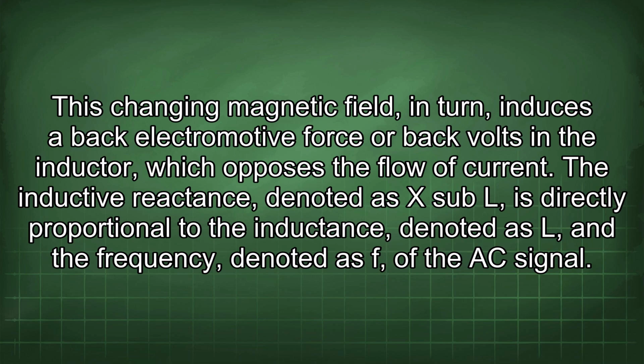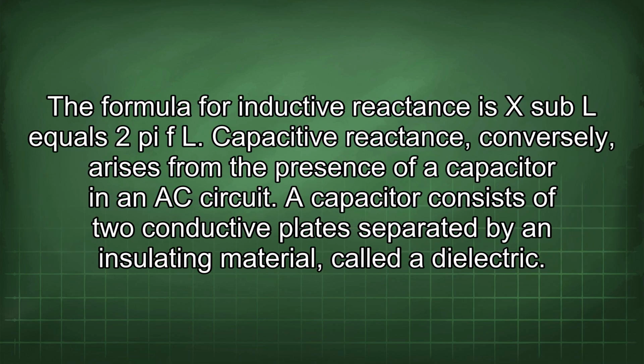flow of current. The inductive reactance, denoted as X sub L, is directly proportional to the inductance, denoted as L, and the frequency, denoted as f, of the AC signal. The formula for inductive reactance is X sub L equals 2 pi f L.